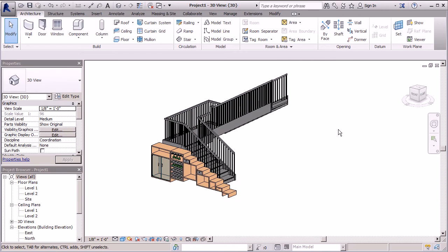But a really powerful thing about creating your own custom family and staying true to the template that you're working with is dealing with the parameters. So let's say we did create this custom family and we dropped them in a project and we realized, oh, we need to make a change to this. We don't have to necessarily go back to the drawing board and redraw this whole model again. We have parameters set in place. In our case, they're very basic, but all we have to do is click on our custom family, adjust the parameters by typing in some values, and those adjustments are made. So there's no remodeling. I'll show you how this works.